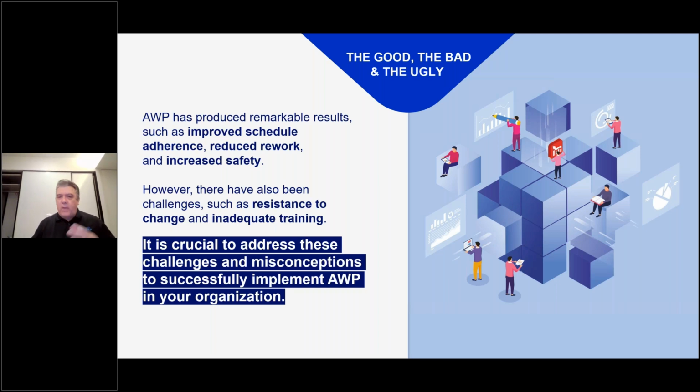What happens if your plan's constantly changing? Well, you can build a plan at one level, which is our construction work packages, which might be an entire contract. I hate to say it, but this idea that a CWP has to be a single discipline, a construction work package, go look it up in Google, it's a construction contract. But breaking those work packages down into discipline parts systematically was part of the technique. And so labeling CWPs, and then CWP doesn't have one level, there's multiple hierarchies of CWPs. But you build a schedule, and it doesn't have to be by CWP, but your CWPs are going to generally align with about the same level as your master project schedule.